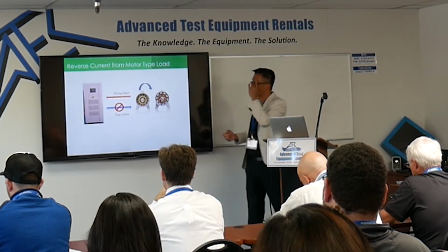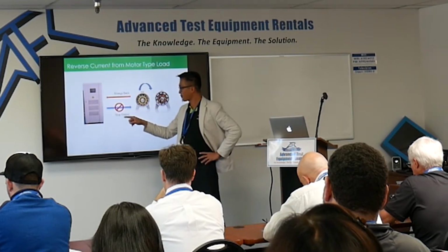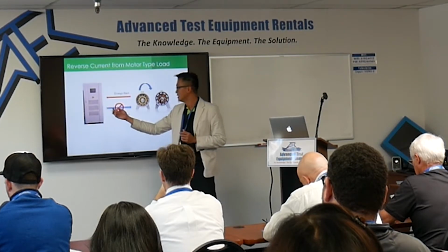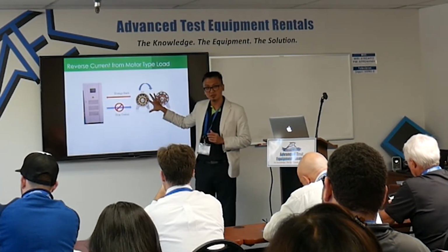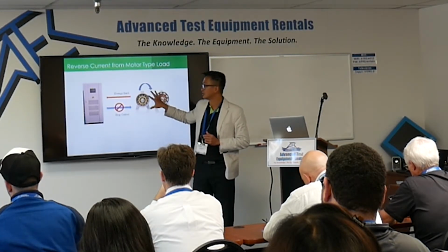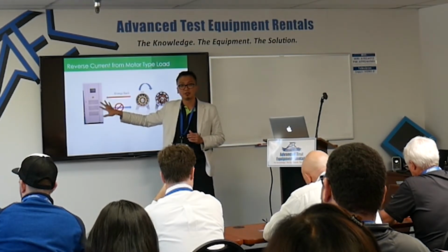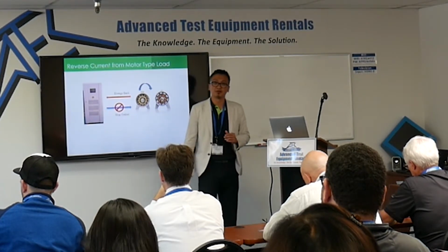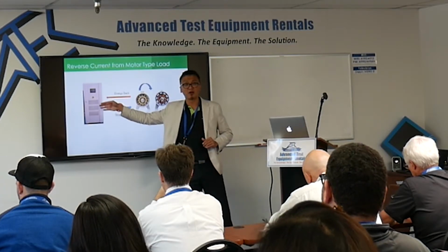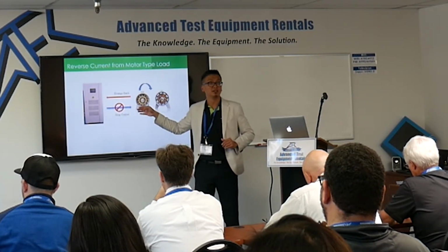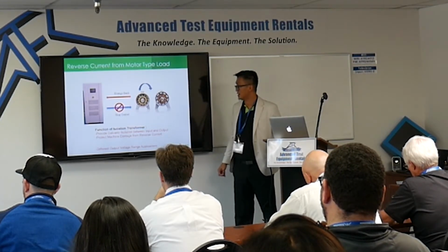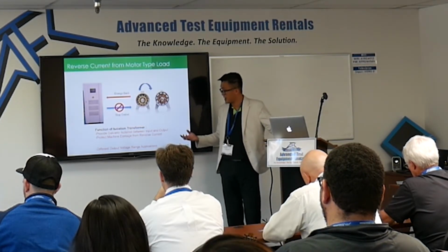Okay. So this is how it works. If the power supply doesn't have an isolation transformer, you output to the motor, and the motor stops there. When the motor stops, energy comes back. You will easily damage your power supply very quickly because the energy comes back to your power supply. You are not sourcing today. So that's the benefit of the isolation.